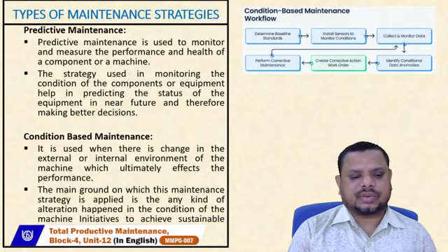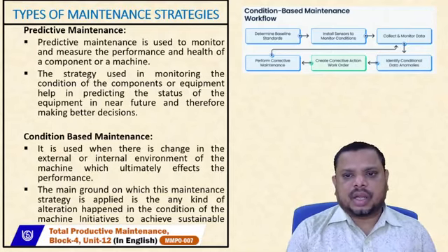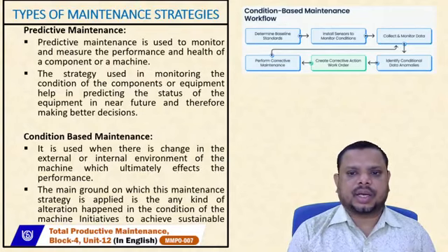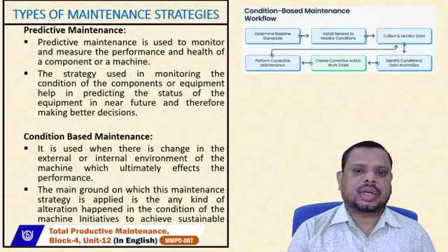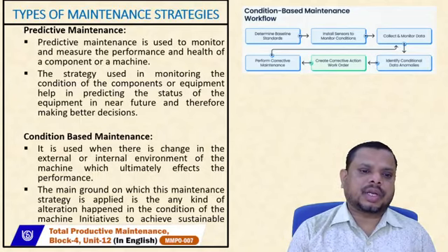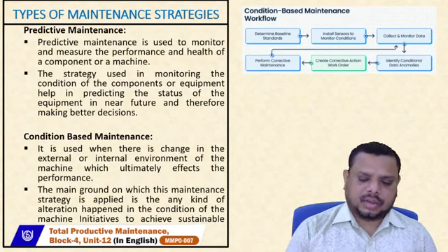First, determine the baseline standards, install sensors, monitor conditions, and collect and monitor the data. Next, identify conditional data anomalies and create a corrective action plan work order. Finally, perform the corrective maintenance, whether repair, adjustment or replacement.